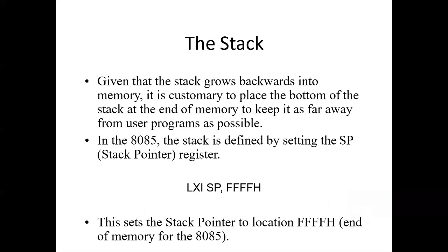Given that the stack grows backwards into memory, it is customary to place the bottom of the stack at the end of memory to keep it as far away from the user programs as possible. In the 8085, the stack is defined by setting the SP stack pointer register: LXI SP FFFFH. This sets the stack pointer to location FFFFH, end of memory for the 8085.